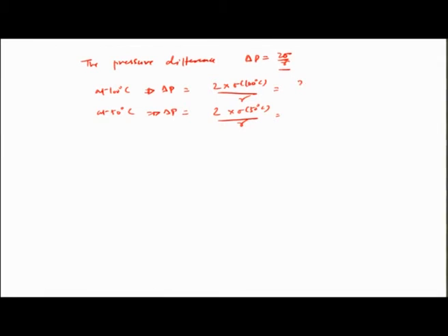So, these are calculated as 2 into 58.9 divided by the radius, a 50 micron radius capillary. So, the bubble size should also be 50 microns for the pumping to happen as the bubble moves forward. So, it is 50 10 to the power of minus 6. And similarly, here this is 2 into 67.91 by 50 10 to the power of minus 6. So, these are the two different pressures which are there at both sides.